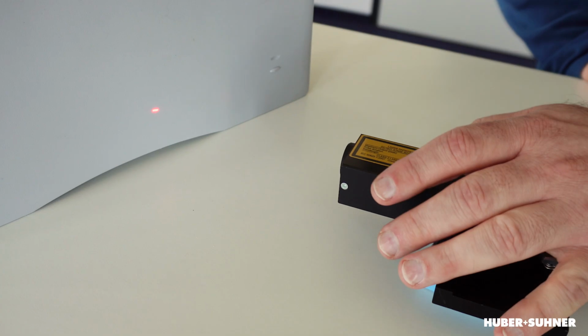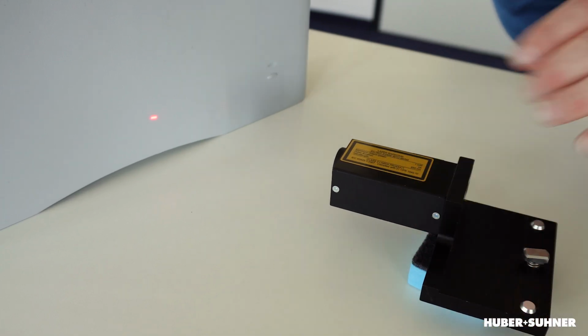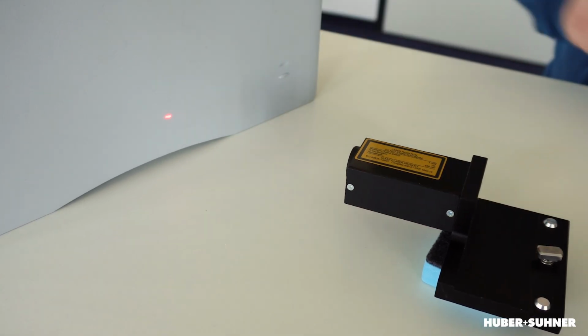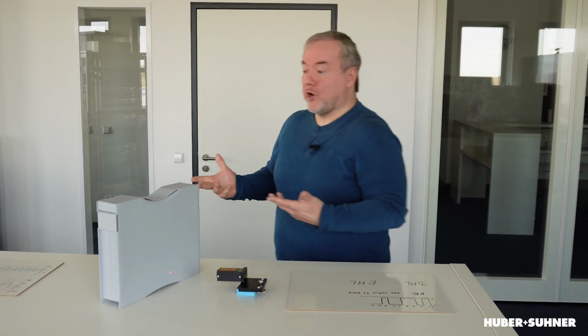There's the so-called direct modulation, the DML, and this means we are taking the laser and switching it on and off. The second solution is the EML, the externally modulated laser. This means we have a laser running continuously, and by means of a kind of shutter system, we can modulate the binary sequence onto the optical signal. So how does this work?